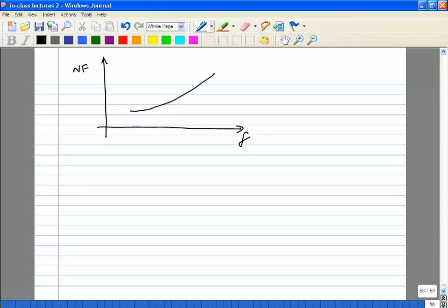And if you look at a common gate, so this is a common source. If you look at a common gate, it starts off much higher, but in a given technology, beyond a particular frequency, of course, common gate will also increase, but much less, and it will increase at a much higher frequency. You might find a point where common gate works better, but you have to actually go pretty high in frequency to achieve that.